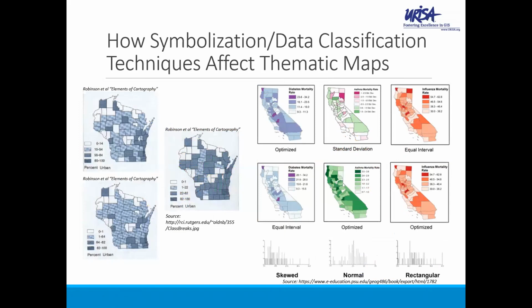We can make it easier for map readers to interpret maps if we match the visual characteristics of the map symbols to the characteristics of the data. There is no standard cartographic sign system that map readers have agreed upon at large that I'm aware of. Cartographers can match any symbol to any type of map feature. However, creating map symbols without carefully thinking about how they may be interpreted is likely to result in map readers drawing incorrect conclusions about what they see.